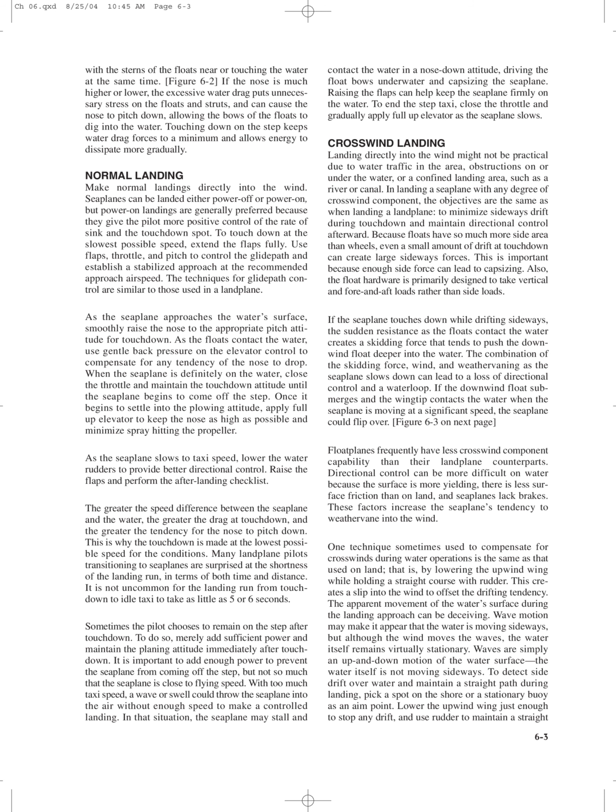Raising the flaps can help keep the seaplane firmly on the water. To end the step taxi, close the throttle and gradually apply full-up elevator as the seaplane slows. Landing directly into the wind might not be practical due to water traffic in the area, obstructions on or under the water, or a confined landing area, such as a river or canal.